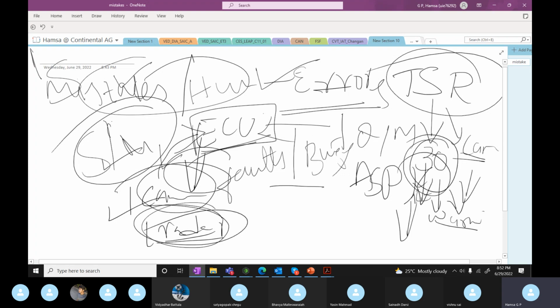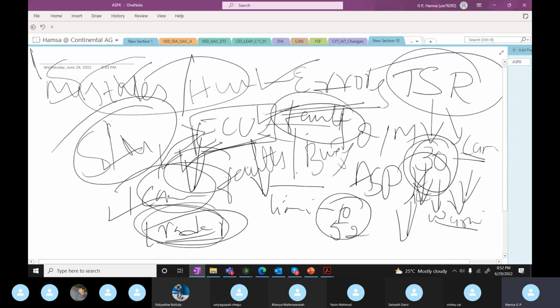What is an ECU? Inside there will be microcontrollers and many other hardware components. So in that microcontroller, what exactly happens? The microcontroller or ECU waits for a limited, specified time. It could be 10 seconds or 5 seconds or 2 seconds. It will wait, and if it still is not getting the camera input, it will set a fault: communication error with the camera. The name could be anything based on the manufacturer requirement, but this is the scenario.